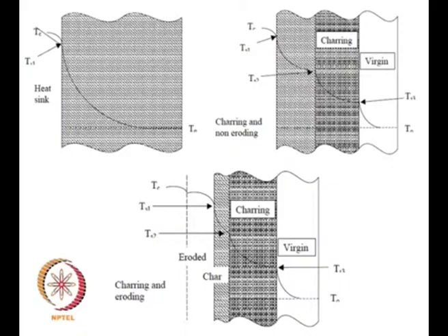Okay. So, if you look at how the heat is going to be transferred, there is a new material that in a sense you are going to have, which is going to resist the heat transfer, right. When you started out, you would have had only two materials, one is the virgin material and the other one is the charring material. As time progresses, you are going to have three layers, with the char layer increasing and the virgin decreasing. Okay. Which means that you can see here very well that the temperature profile through these decreases, and on the other side you can have a very low temperature.